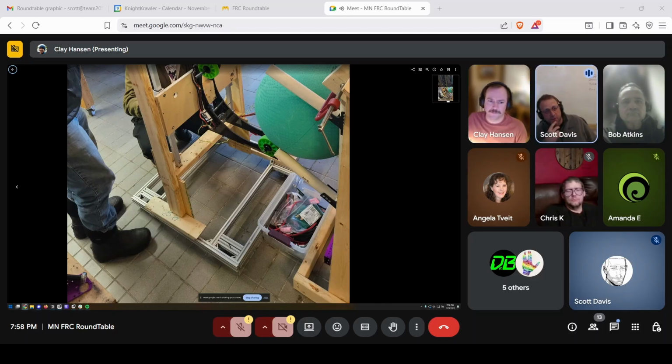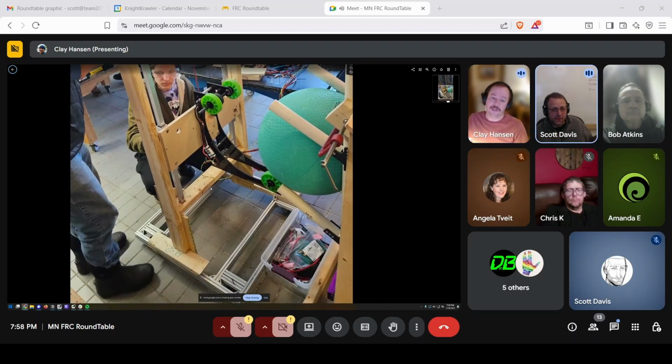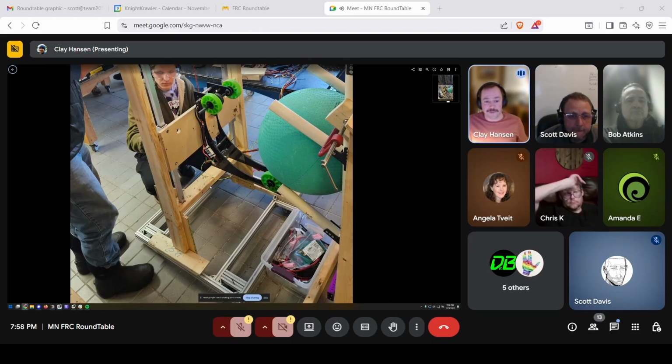It looks to me like you're controlling those motors with CAN. Teach me, how do you get an Arduino to control Spark Max over CAN? Yeah, so both CTRE and REV controllers are actually capable of running off PWM. And though that is a twisted CAN pair, it is just a 5-volt PWM signal. The current version is just using a hardware PWM output set up to the duty cycle range that FRC and the radio controlled aircraft community use. Basically the way it used to be controlled before CAN bus was implemented.